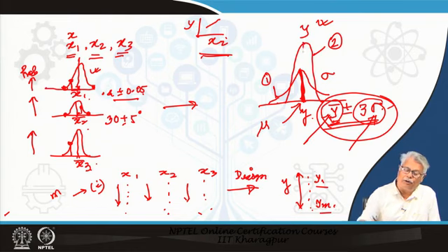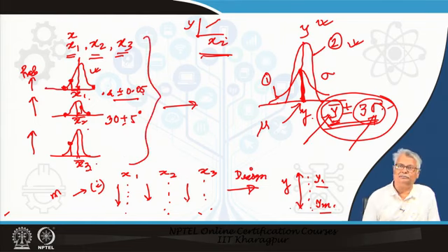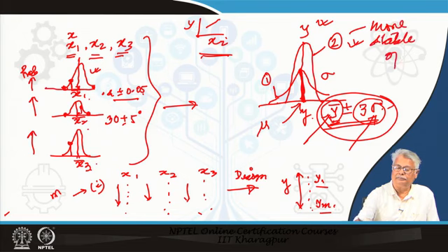Now, it is obvious that my second design is less affected by the random variation of the input parameters. That means, even if my input parameters deviate from the design case values within normal limits, my output parameter will remain fairly okay. That means my second option is a more stable option. And how do we decide it?